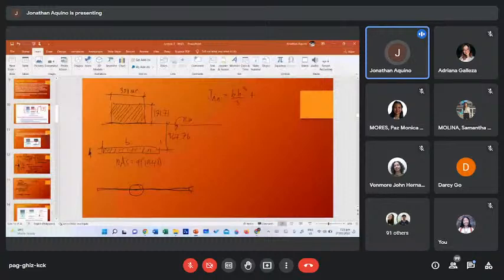So the moment of inertia about the neutral axis is simply 300 times h, and our h is 171.71, cubed over 3 plus A d squared. Our A here is equal to n times As, so 9 times 1,940 times d, the distance from the centroid of the steel to the centroidal axis of the section, 367.76.